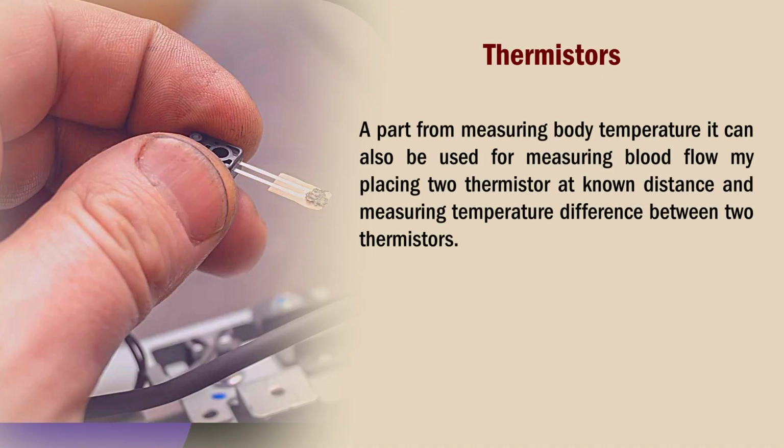Its response is faster as compared to RTD, but it has an exponential temperature versus resistance response. Apart from measuring body temperature, it can also be used for measuring blood flow by placing two thermistors at a known distance and measuring the temperature difference between the two thermistors.